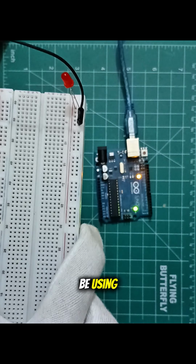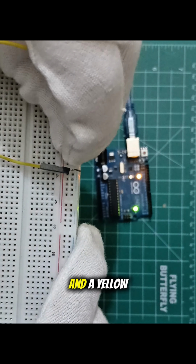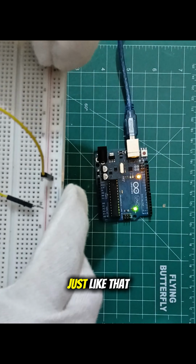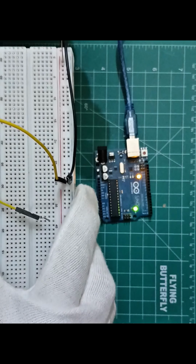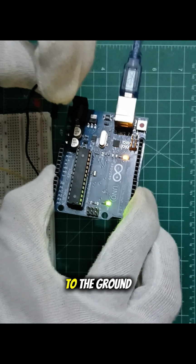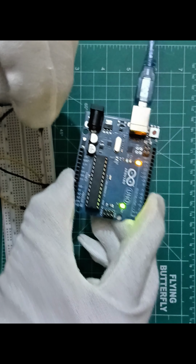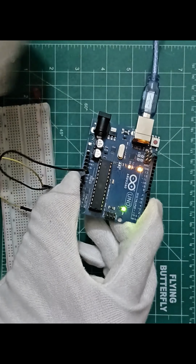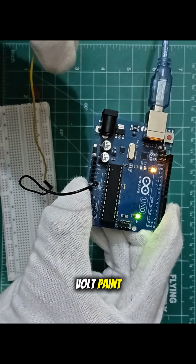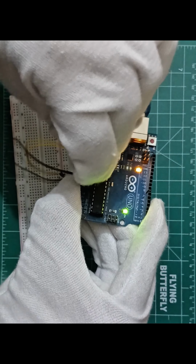Then we will be using a black wire to connect from the negative of this LED and a yellow wire from the positive of this LED. Just like that. Then we will be connecting this black wire to the ground pin of this Arduino, like that, and the yellow wire to the 5 volt pin, or you can also use the 3.3 volt pin of this Arduino.